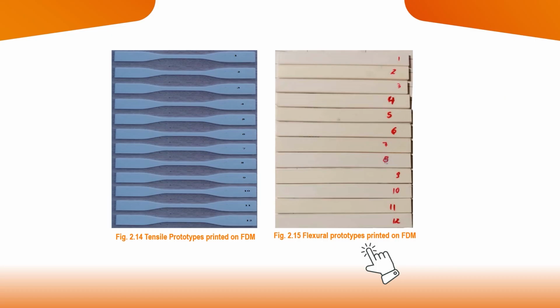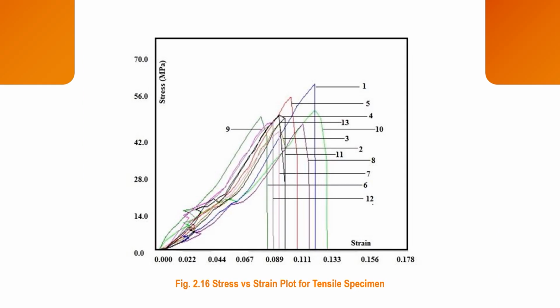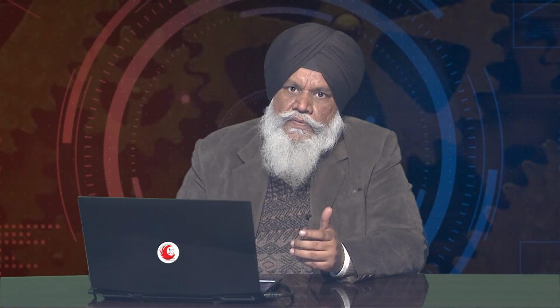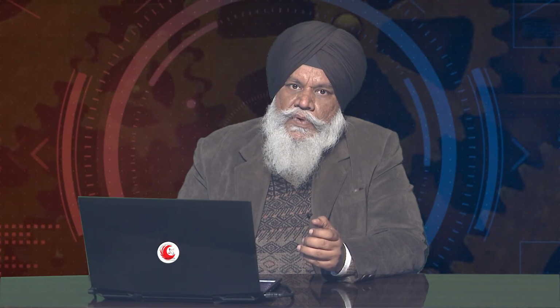These were put on the UTM, and we tried to measure their peak load, peak elongation, break elongation, peak strength, break strength, and modulus of toughness. For the tensile case, all the stress strain curves for these 12 cases are plotted. As a simple thumb rule, the area under the curve represents the modulus of toughness. So a higher area under the curve is a symbol of more impact resistance property of that material.